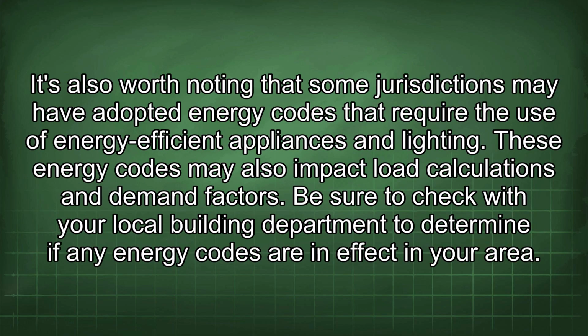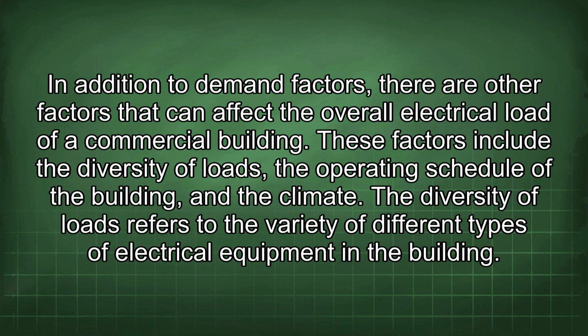It's also worth noting that some jurisdictions may have adopted energy codes that require the use of energy-efficient appliances and lighting. These energy codes may also impact load calculations and demand factors. Be sure to check with your local building department to determine if any energy codes are in effect in your area.